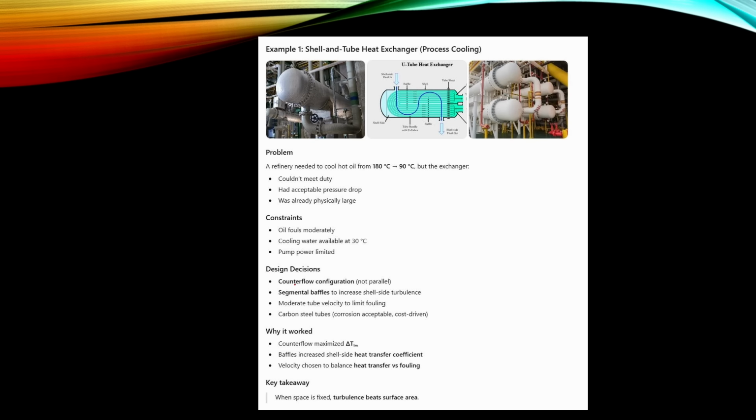So the counterflow configuration has solved this problem, and there are also these baffles to increase turbulence, and moderate tube velocity to limit the fouling, and carbon steel tubes.